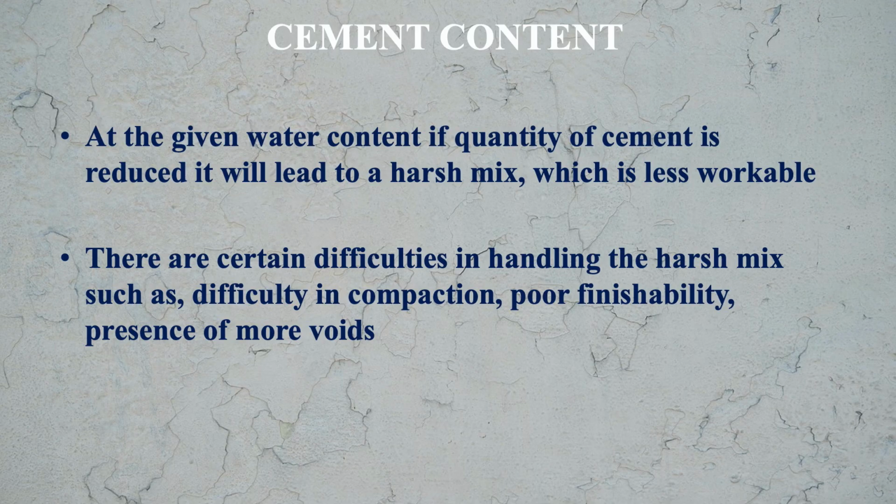Concrete will be less workable. There are certain difficulties in handling the harsh mix, such as, what are these difficulties? Difficulty in compaction, difficulty in finishing, means you will get a poor finishability, then the presence of more voids will be there. These are the problems working with the harsh mix.